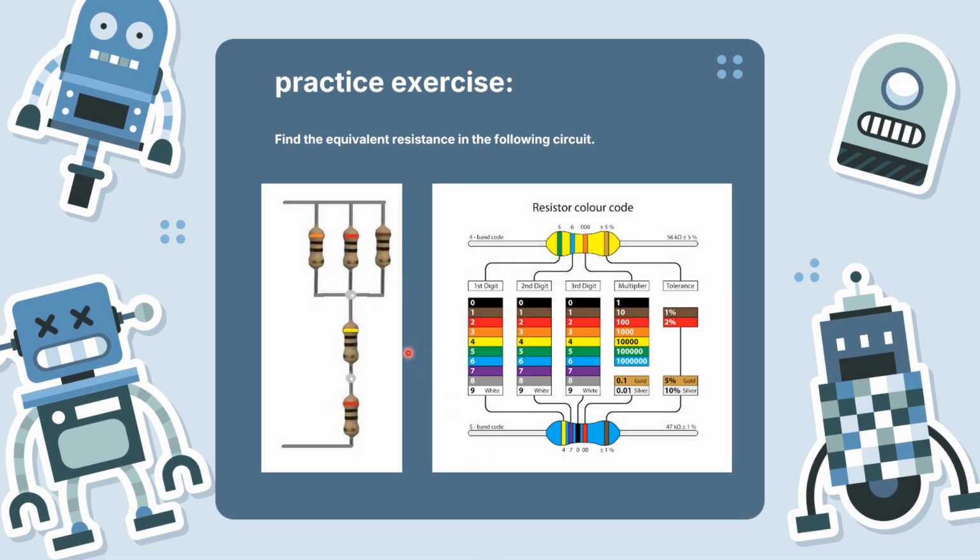Well, to read the value of a resistor from its body, they don't directly print the resistance value number on the body, and that's why we need to read the resistance value from these color coded numbers, and these colors look like this, as you can see. First, we should note that we should start the color values from the direction where the 3 colors are close to each other, and not from the one that is far away.